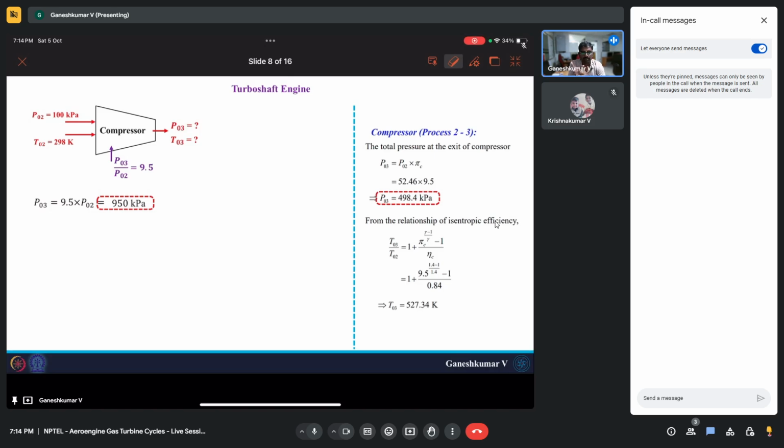However, the pressures across which this compressor is operating at the flying condition is lower compared to the ground condition. So the absolute value of that pressure across which it operates should have some effect on the work done by the compressor, because these are not ideal compressors.